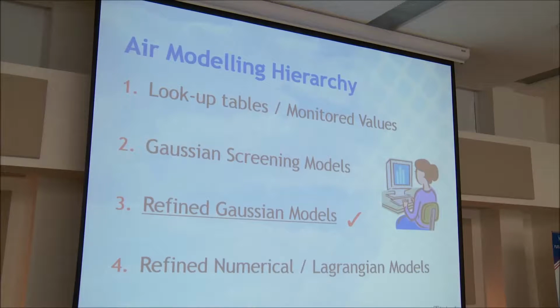All right, so we don't necessarily want to dive into the most complicated model when going into an odor assessment. Typically, there's a hierarchy in which you strategically proceed down in terms of complexity. To make a long story short, the refined Gaussian models are recommended for a good odor study involving many different sources at a facility and understanding what the impacts would be at many different receptors around the facility.